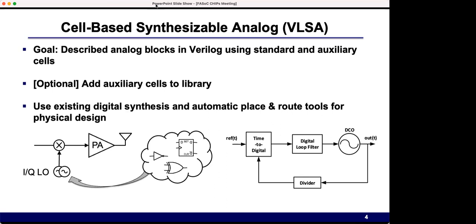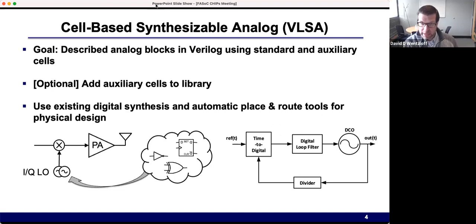Okay, thank you. To contrast, structural Verilog means you're actually typing AND gate, put an AND gate here, with the inputs A, B, and the output Z, for example, or put a D flip-flop here, or put a tri-state buffer here. That's structural Verilog. It's really annoying, but it lets you pick specific cells and wire them up exactly how you want. And then you can tell the tool to not touch it. Don't optimize, don't treat that like logic, don't optimize anything I just did, just leave it. But then I'm going to combine that with a bunch of other digital functions, adders, multipliers, whatever, in behavioral Verilog around that to complete the whole design.